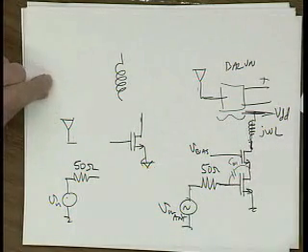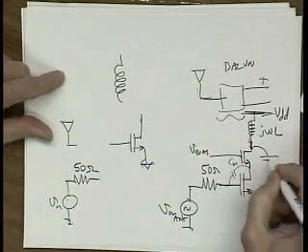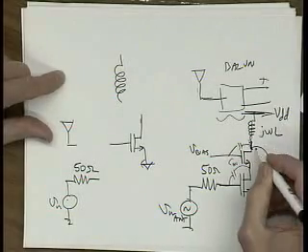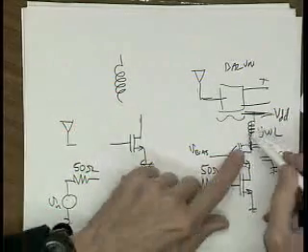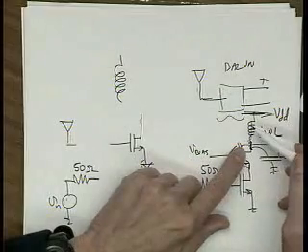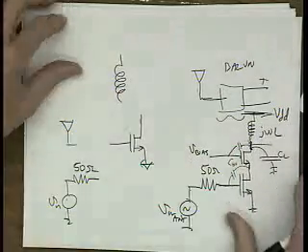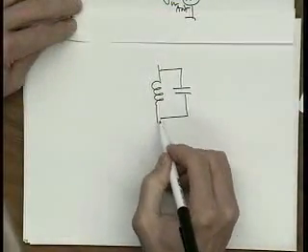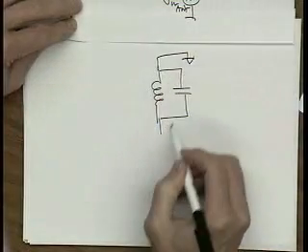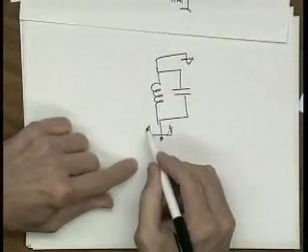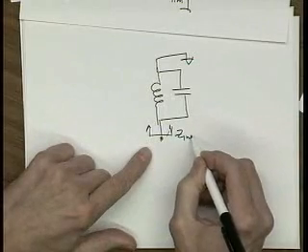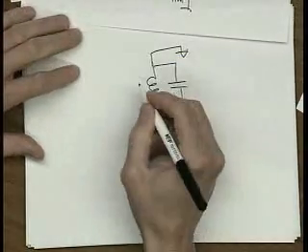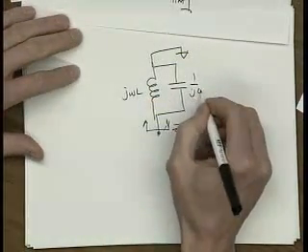Here's the other reason inductors are just great. We've got a capacitance hanging out here from all sorts of stuff, capacitance to the next stage, and so on. C load. So I've got a capacitor and an inductor together here, in parallel. So let's look at the design of that. So this is grounded. And let's look up into the impedance of this. What is the Z in of this circuit? Well, this is j omega L, and this is 1 over j omega C.